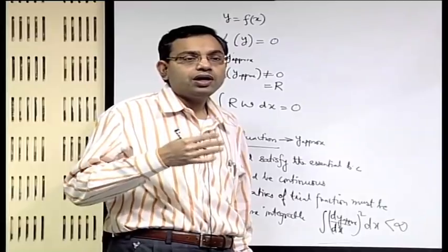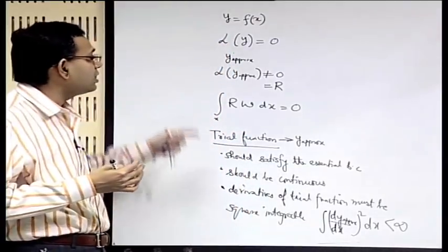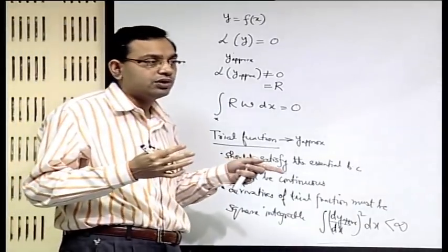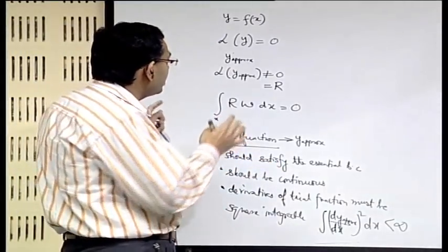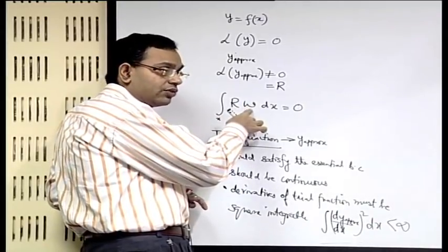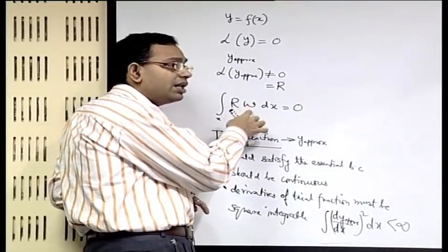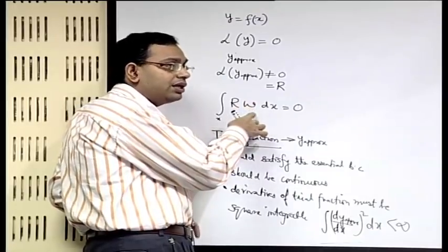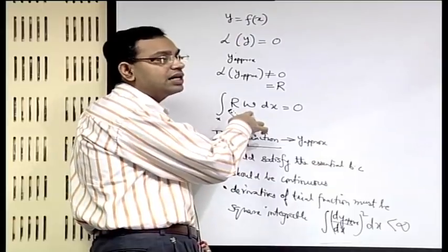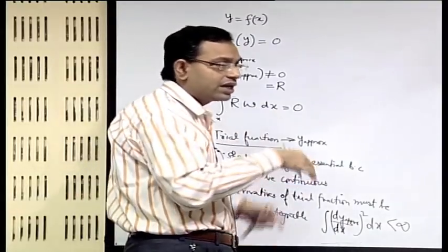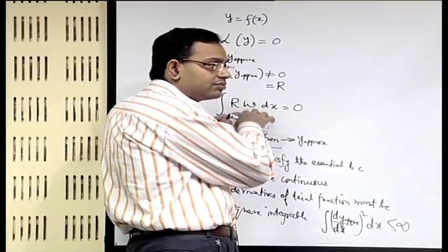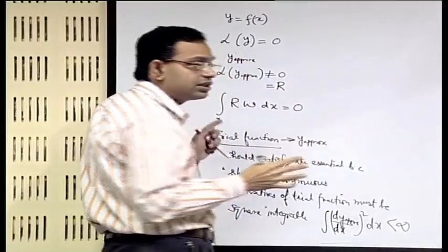So, you may also have the weighted residual method implemented without going through the variational formulation, because variational formulation gives us a clue that you have to multiply this with a weighting function. The weighting function has a similar meaning to that of a variation, but it does not mean that you have to go through the roots of variational formulation. We will see that you can have any arbitrary choice of the weighting function, of course consistent with certain constraints.